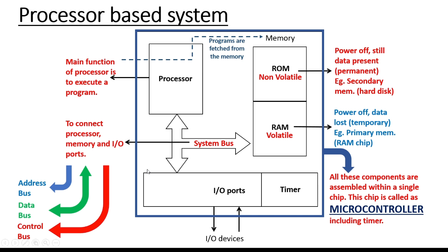But if you look at the larger picture, if you use the hardware delay in your system, it does the job of counting, or producing a delay, and meanwhile your processor gets free. What if you are using software delay? Software delay is nothing but instructions which are repeatedly executed.